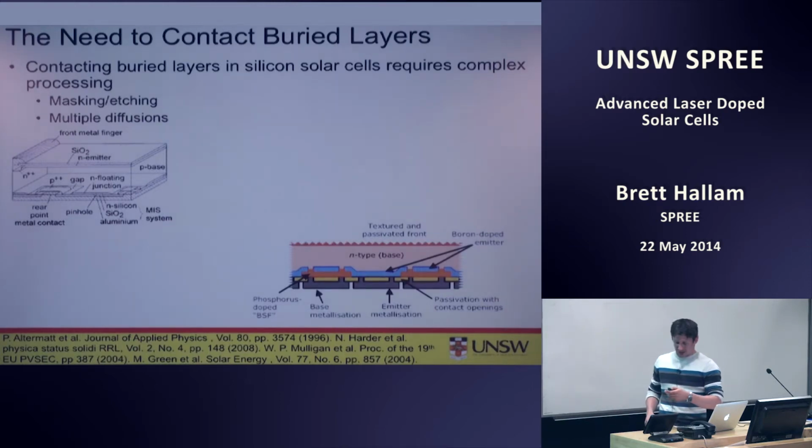If we take a different technology, which is the buried emitter solar cell, so it's an IBC solar cell where essentially they do a full area emitter diffusion, but this is patterned in prior to the diffusion to stop the diffusion occurring in localized regions which will subsequently form the base contacts. And then they do the opposite diffusion, again requiring a mask diffusion process so that they can locally define where these diffused regions go. And during the second diffusion process, it actually pushes the emitter further into the solar cell.